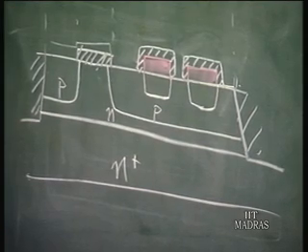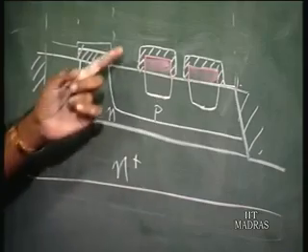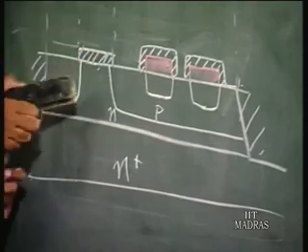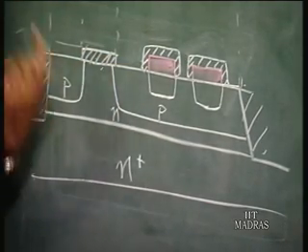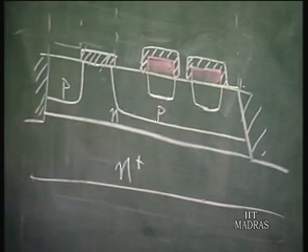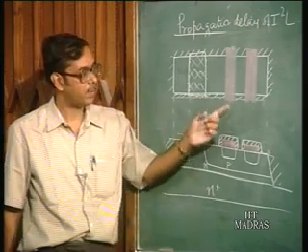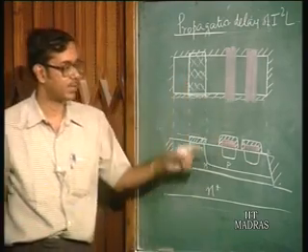You understand? So what you have done is grown oxide and etched back, but you still retain some oxide on the polysilicon. So you have oxide here and here and here. Silicon dioxide is an insulator. That is the important property of silicon dioxide which should be utilized here. Now what do you do? Basically you did not require any mask here for this process.